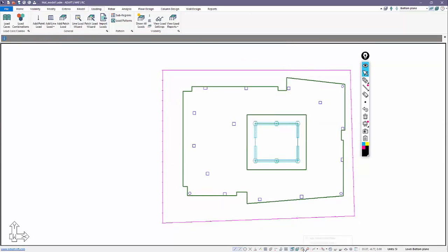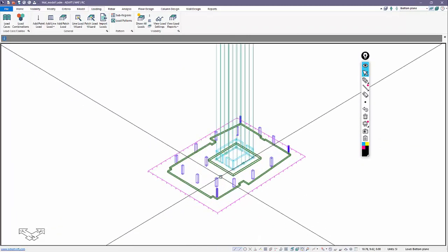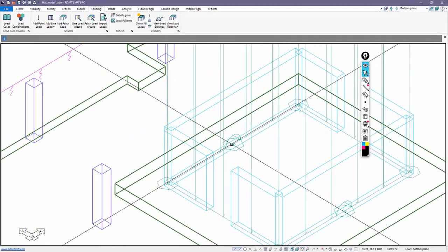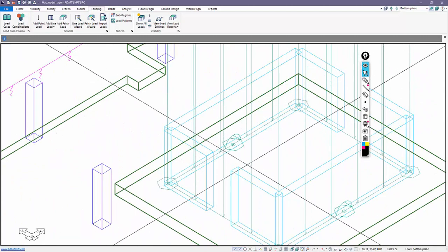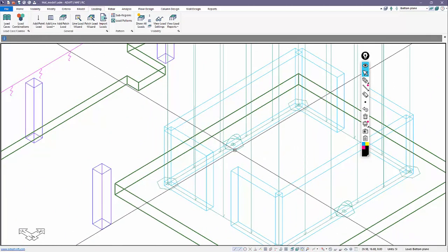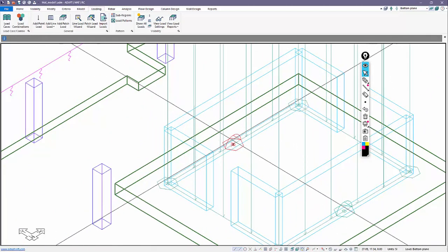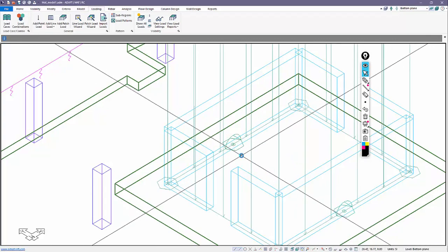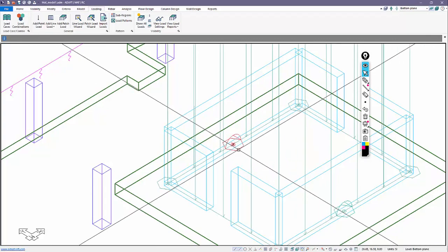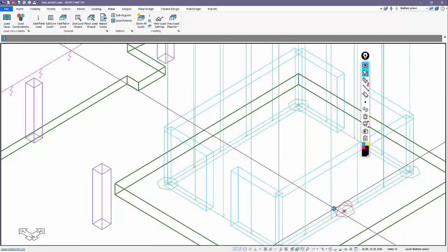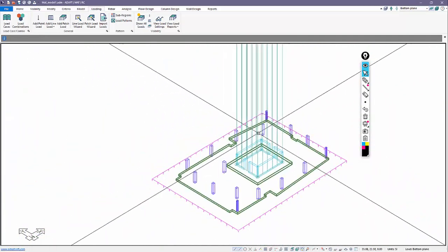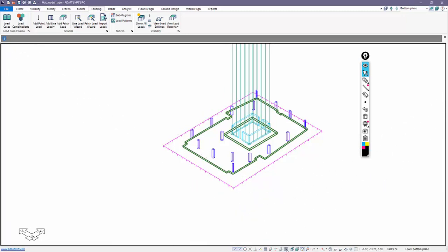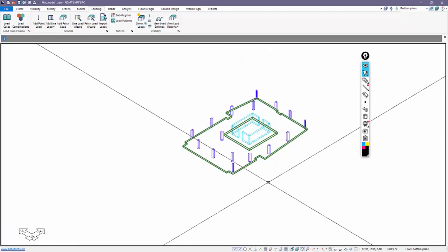And so if I click on snap to midpoint, notice that allows me to snap to the center. And then rotating this again to multi-story view, you can see the direction. Positive moment is actually entered as a clockwise sign. So this clockwise positive is the notation for, or the sign convention for the moments. So that's how we would enter moments on the slab. We'll go ahead and go back to our default display.